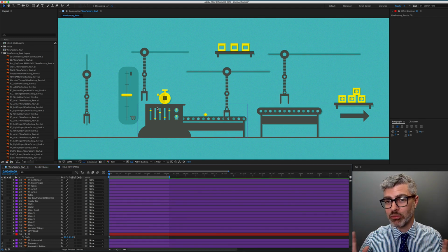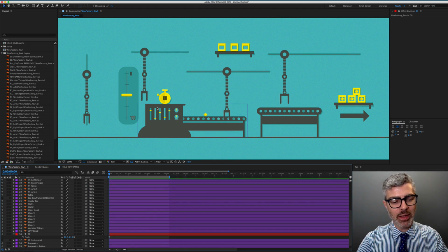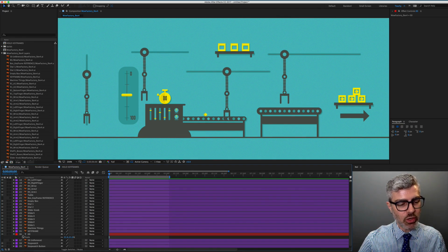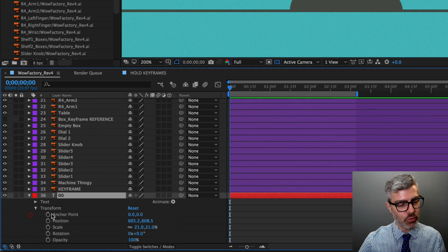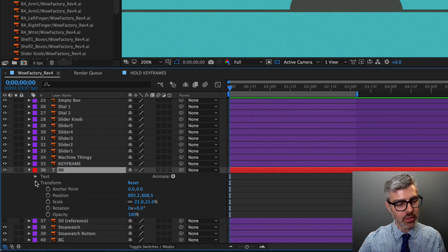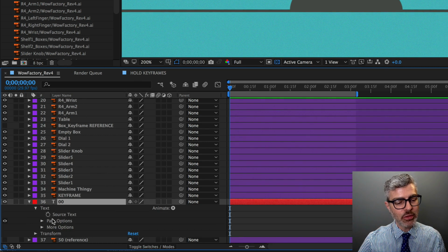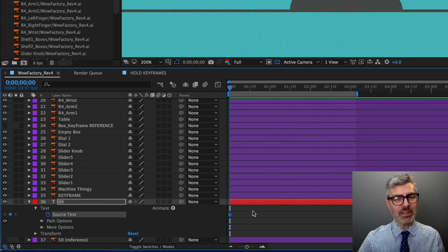Now this isn't going to be really great fluid animation. And in fact, I need to tell you about a different kind of keyframe that you need to know about in order to do this animation. Because we didn't do this in the animation oatmeal example, but if you twirl down this little tab for your type, and instead of looking at the transform properties, we look at the text here, there's a thing called source text, which you can actually make a keyframe for. So when you make that keyframe, though, it's going to have this unfamiliar square shape, okay? And that's what's known in After Effects as a hold keyframe.